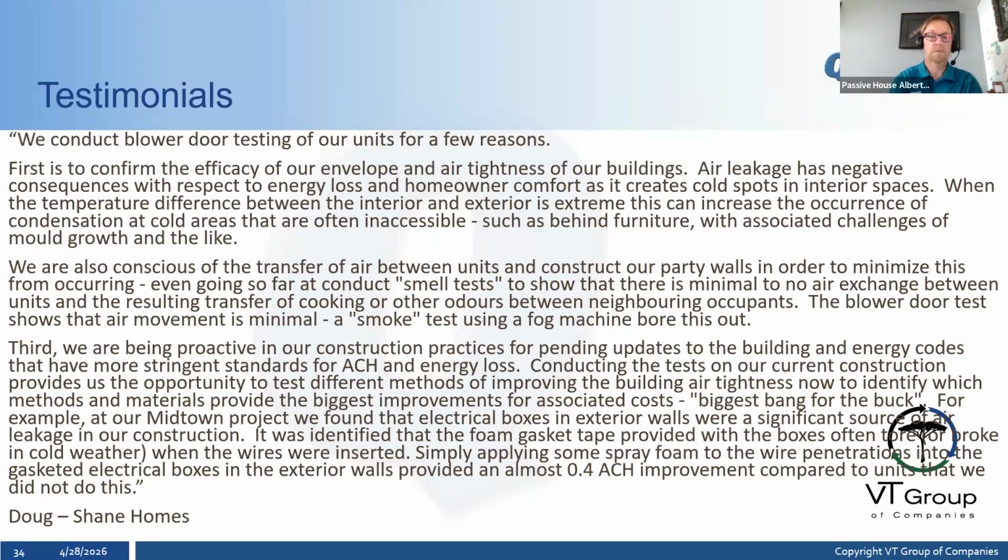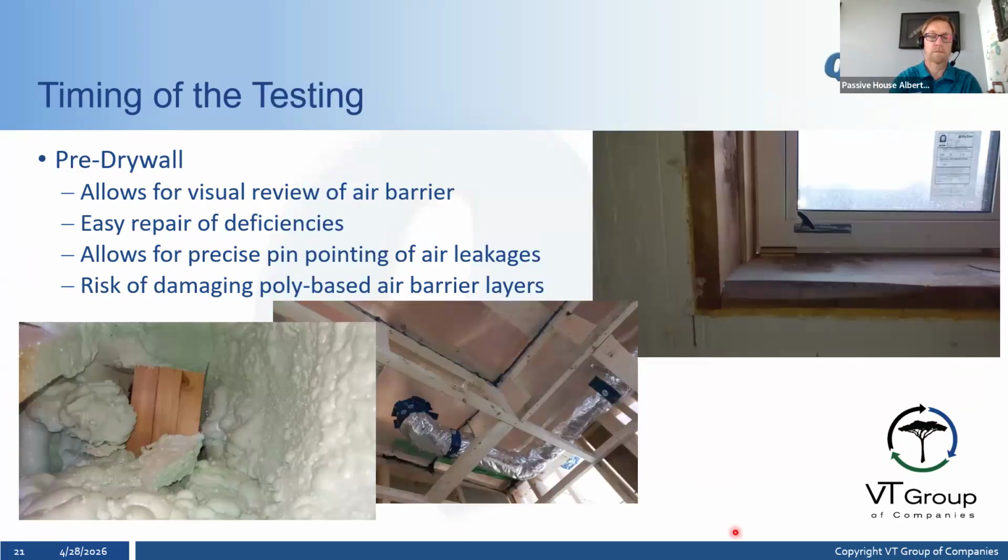Yeah. Okay. Let me see. I'll go to this one here. So when I'm doing my thermography between May and October, it's a little hit and miss sometimes. Depends on the time of day, depends on the weather. So I'm trying to do both, right? My process when I go and do a mid construction is I walk around the house first and I look at everything. I look at all floors. I start in the basement, work my way up, and then come back down and set up my fan if we're good to go. Then I do my air tightness testing for metrics.